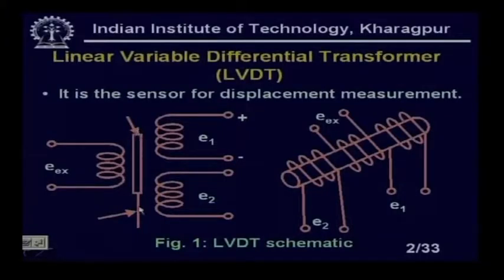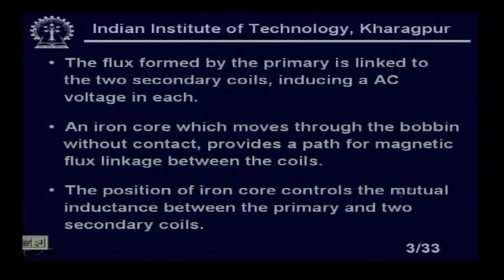Welcome back to the classroom again. We have seen the construction of an LVDT and how it works. If you look at this core, it will move up and down, and I will get different mutual inductance, the voltage also will change, and there will be a phase difference between the input and output. That is what we have written in a nice way.